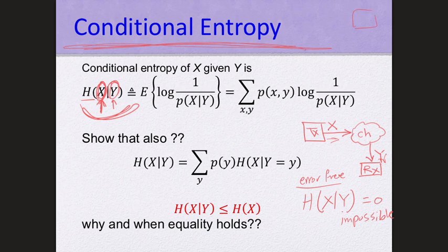If you have two receivers, same signal transmitted from the source, and it's read by two different receivers, RX1 and RX2, then you have noise 1 and you have noise 2. They are not the same. But if you have two signals coming from two sources, but they are both received by the same receiver, then you have only one N, one noise only. So the noise is always related to the receiver, okay? The random changes in the signal due to electronics are always tied to the receiver, not the transmitter. That's one important concept as a refresher for your communication.